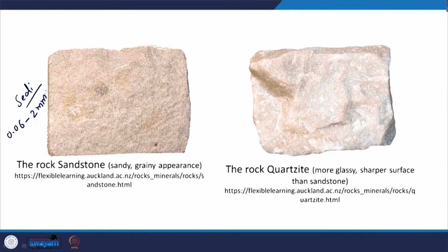It is gritty to touch like sandpaper. If it is soft, then generally of no use, but if it is hard, then it can be used as aggregate or fill etc. in the construction and highway industries, dimension stone for buildings and pavings etc.